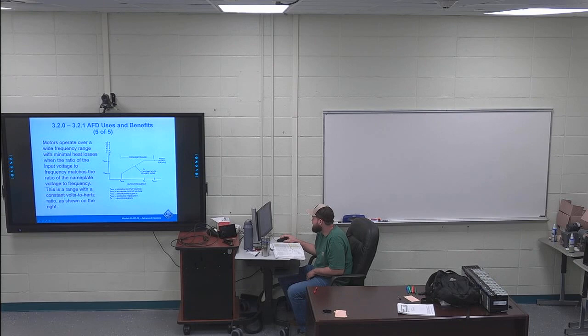And then once you reach the base frequency, from the base frequency to the maximum frequency, you have constant voltage. Highlight that. So you want this section here highlighted for constant volts to hertz ratio, and then this section right here, you have constant voltage. Your output voltage doesn't change from your base frequency to your maximum frequency. So those 2 sections you want to mark on this picture.